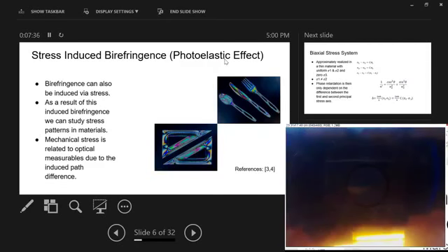But the component of birefringence that we're interested in here is that due to stress induction, and this is known as the photoelastic effect. So essentially, this comes about when an object is stressed. The quote-unquote crystalline structure of the material is deformed, and as a result, the dielectric tensor changes. And for the purpose of our experiment, we say that this relationship is roughly linear. But we have a couple examples of birefringence induced in plastics shown over here. Common silverware and protractors are pretty illuminating examples.